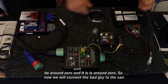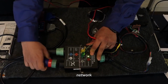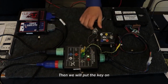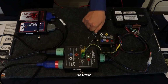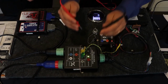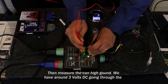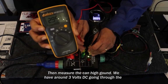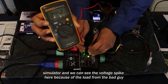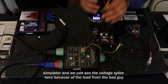So now we will connect the bad guy to the CAN network. Then we will put the key on position, then measure CAN high to ground. We have around 3 volts DC going through the simulator, and we can see the voltage spike here because of the load from the bad guy.